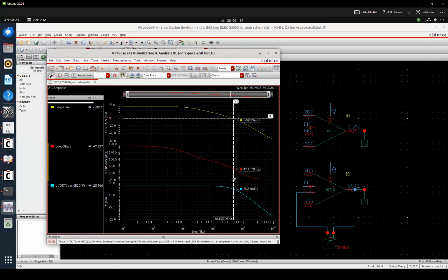So this means that there is a feedback loop, and as long as there is this much loop gain in this range, this unity gain buffer works as a buffer. So it determines the unity gain frequency of the loop gain. That directly determines the 3 dB bandwidth of the closed loop response. That is a key point of this feedback analysis.